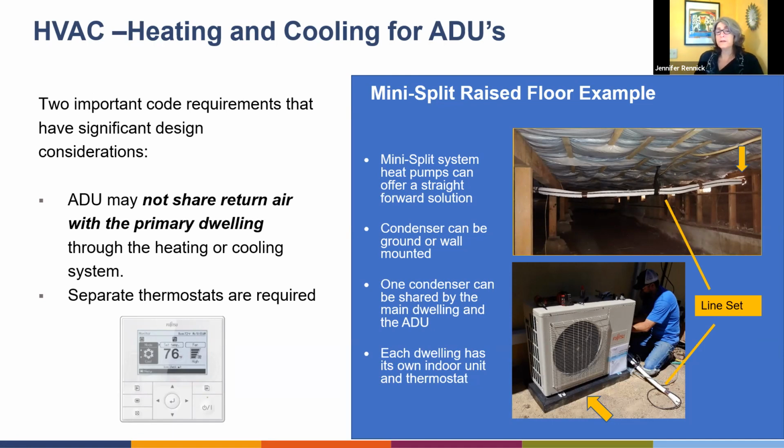It's possible if you're redoing the whole project, you're redoing your whole system, it's okay if you have a specialized system where you have one outdoor unit that controls separate indoor units, as long as they can each have their own thermostat and not share the return air.